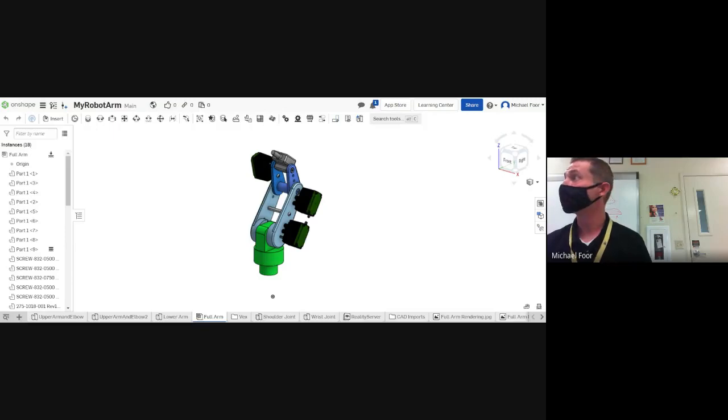Mr. Four, I have a question on the 3D fixture. I have all my parts here, so can I print that? Is that the best way to put these three? Yeah, I would make them a little bit closer, because the head is going to have to move around a lot on there. And let's send it to the CR10 because that's a little bit more trustworthy. Get them a little bit closer because the more this has to move around, the longer it takes. So give it about an inch in between each part. Okay.